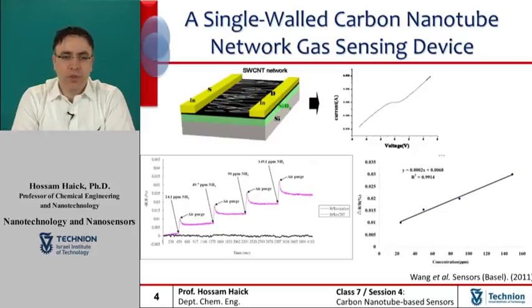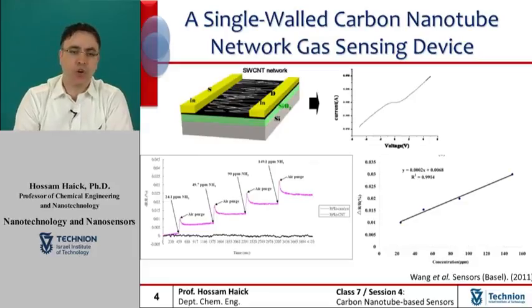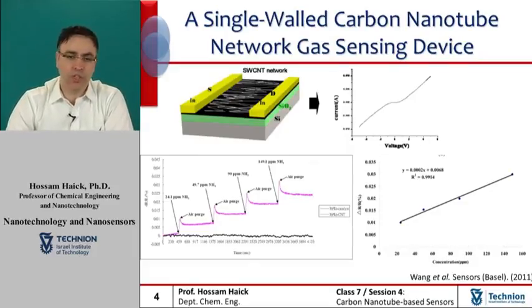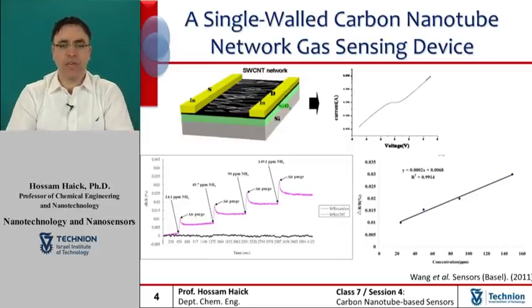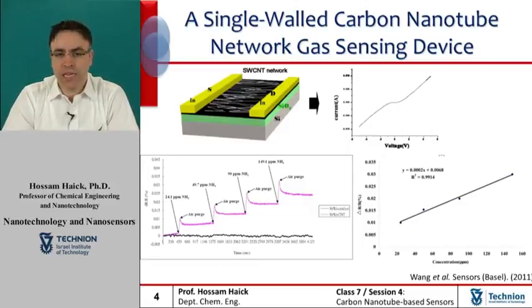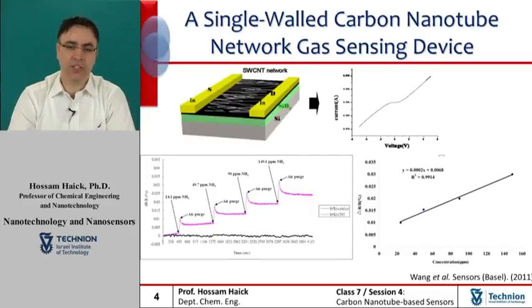An alternative approach to the use of sensors that are based on individual carbon nanotubes is the application of a random network of single-wall carbon nanotubes. Using a random network of single nanotubes circumvents the requirement of position and structural control, because the devices display the averaged property of the carbon nanotubes. An additional feature of the single-wall carbon nanotube networks is that they can be processed into devices of arbitrary size using conventional microfabrication technology.